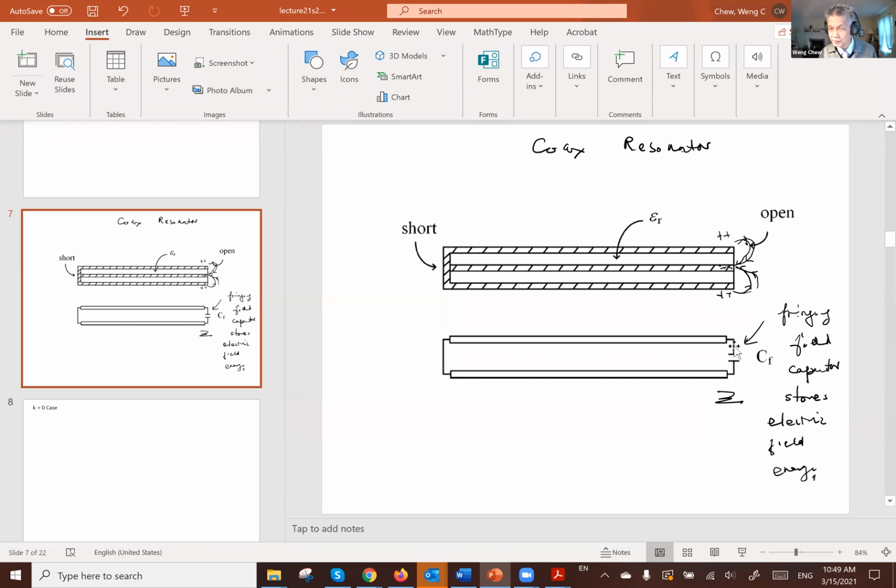Well, if you were to put in a capacitor here, you will have some transcendental equations to solve, okay? So one way to solve transcendental equations is to use graphical methods, but I'll leave it for you to play around with if you're interested in finding the resonant frequency of this transmission line. But when this is an open circuit, finding the solution is trivial, okay?